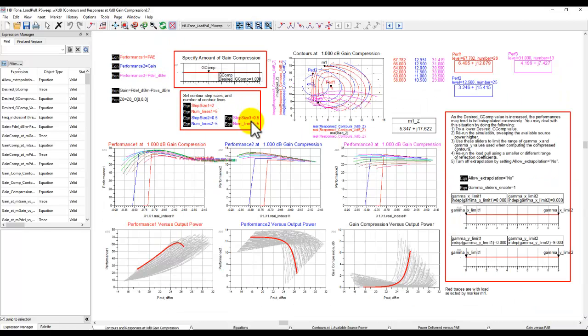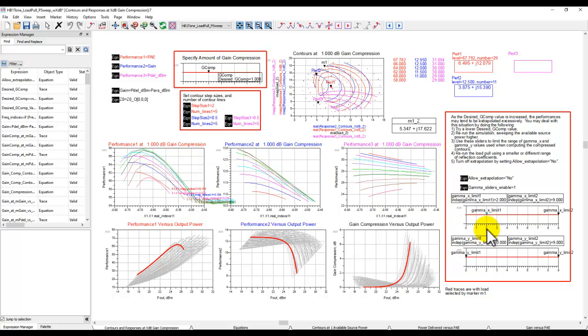And again, as I said, not all the data sweep points of load reflection coefficient are going to give you the desired result. Here you can see some weird looking curve because at certain rho imaginary or real axis, you are not getting any sensible data which is meeting the minimum criteria. And using these two sliders, you can limit the gamma in X. For example, I only want to plot from index number 2 to 9 by moving this slider. And now you can see these plots get updated only for the region of the Smith chart where you wanted to number crunch data.